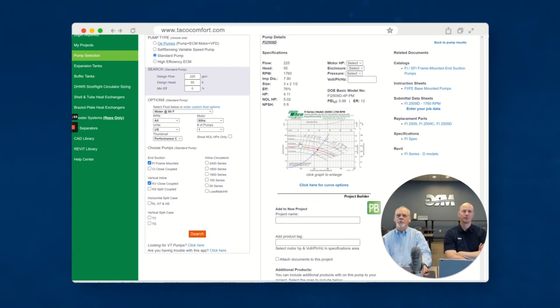That way you have a pump that can be used, because a lot of times they may change part of the design later. They may not have the building completely utilized. Yeah. And if they add some more equipment, you may need to have some more pump. And you can do that by changing the impeller size if you have that available and still use the same pump.